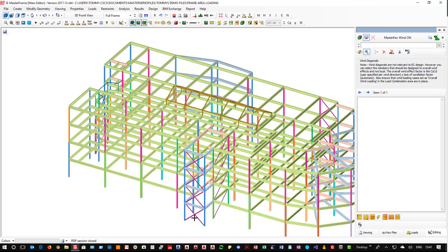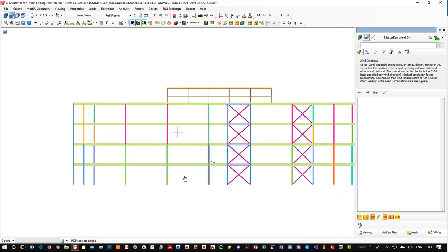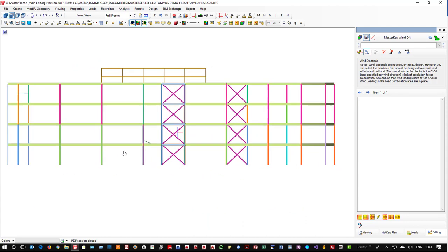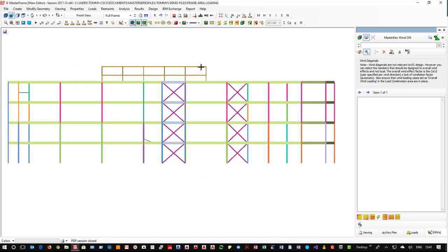You don't do that in Eurocode, but you identify globally and locally loaded members. So that member's locally loaded, that member's locally loaded. These members here are globally loaded, the bracing. So what I need to do is to tell it what members are all my bracing members. This is for the A value, not for anything else.